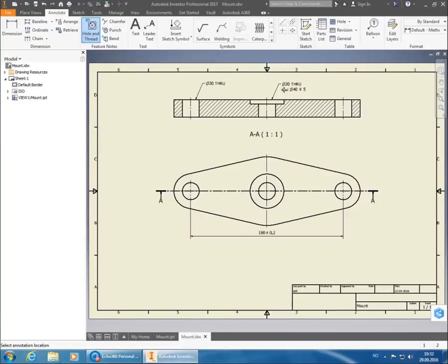And you can see that I'm getting a lot more information here. So what it's showing me is that I have a 20mm hole that's going all the way through, but on one side I have a counterbore that has a 40mm diameter, and that one is going 5mm deep. So the counterbore is sort of almost a rectangle shape without a top.